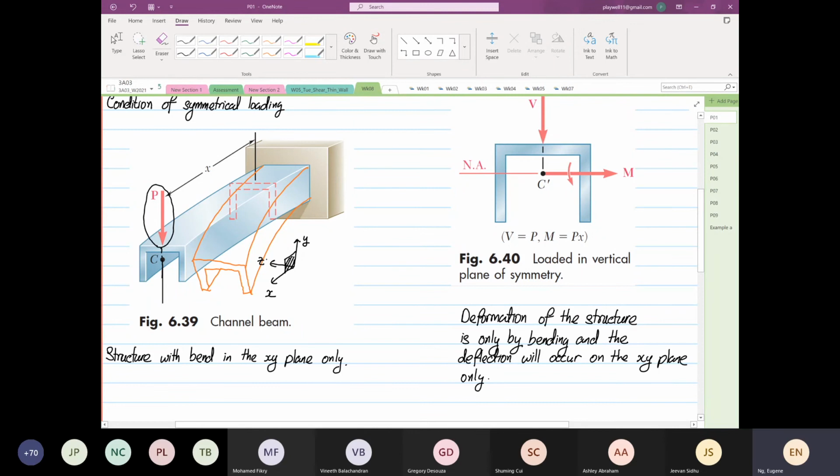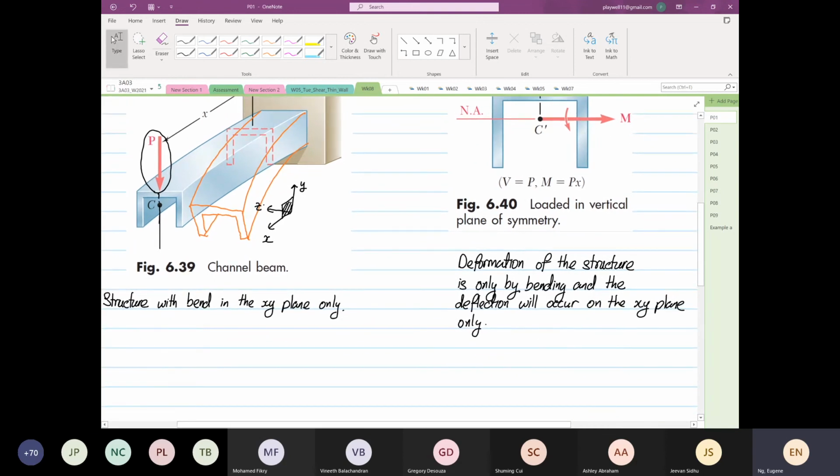Okay, so there are two general formulas that we're going to apply to analyze the structure over here. The first formula, as you all know, if we have force P at the end of the cantilever beam, the formula we're going to apply is stress sigma x is equal to minus My, sorry, it's not My, Mz, because the moment is about z, over Izz and multiply by y.